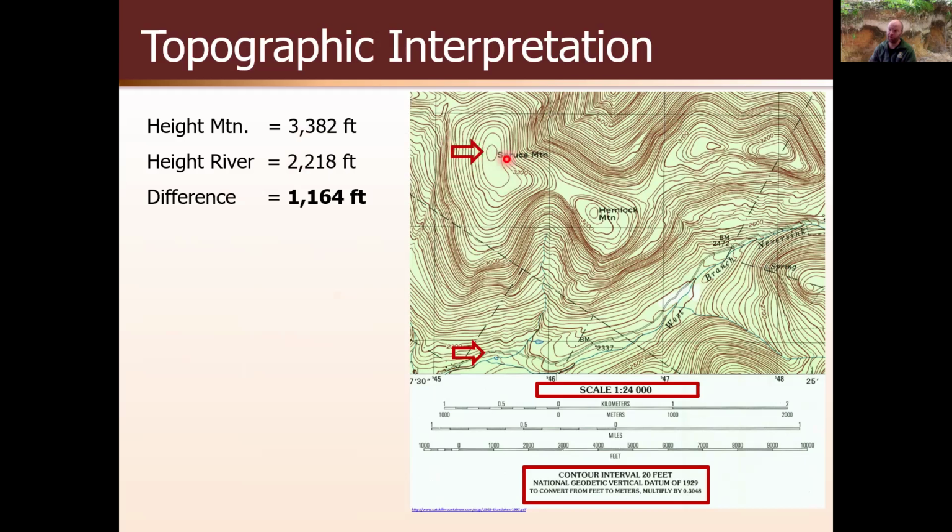So first, you maybe are thinking, how high is that mountain? So you can use these contours. Here's 3,000, and going up, here's a bolded line marked at 3,300. So 20, 40, 60, 80. There are 4 more contour lines above that. So remember, concentric rings represent a mountain. So you're going up to 3,300. You keep going up. There's not another bolded line, so we haven't reached quite to 3,400. And so here we're at 3,000 to 3,400.